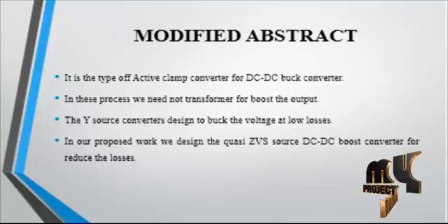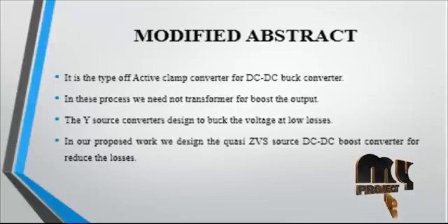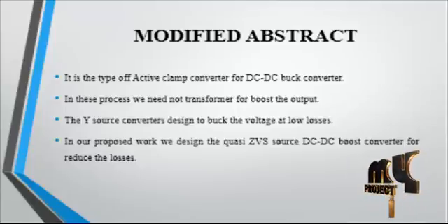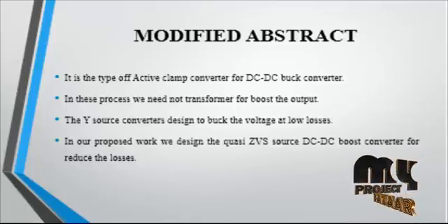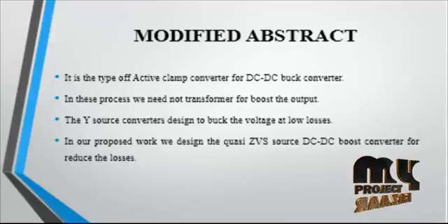The conventional graphical approach fails due to the coupling between the filter inductor current and the resonant inductor current. An analysis that takes into account the presence of resonant elements is presented to establish the condition of stability. This method correctly predicts the stability of current controlled active clamp converters.